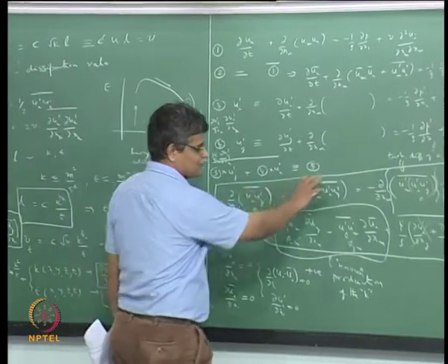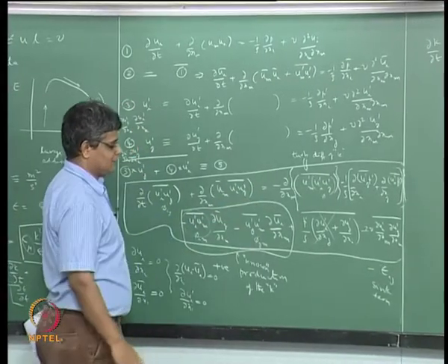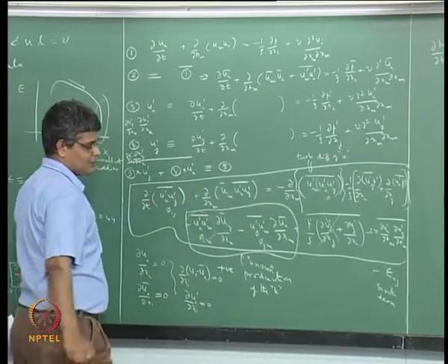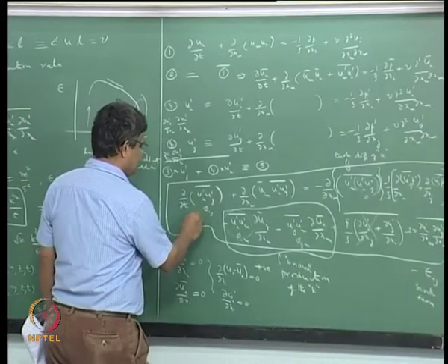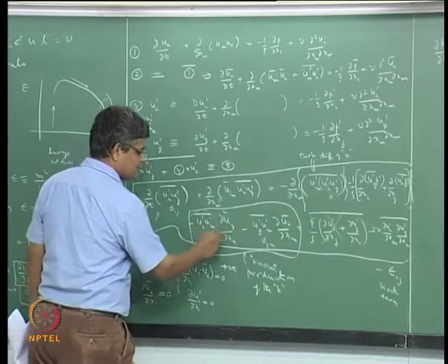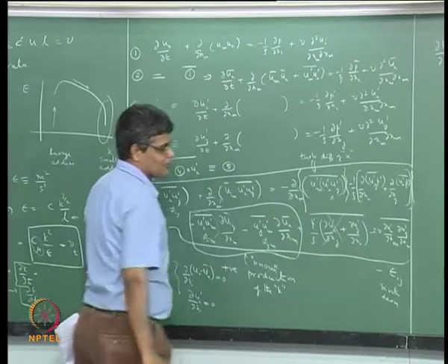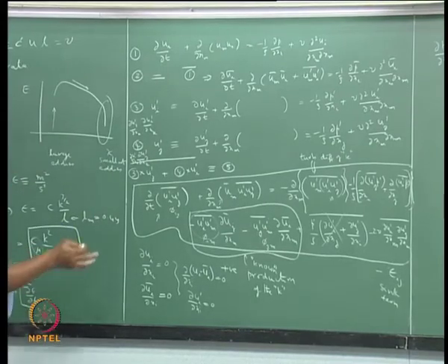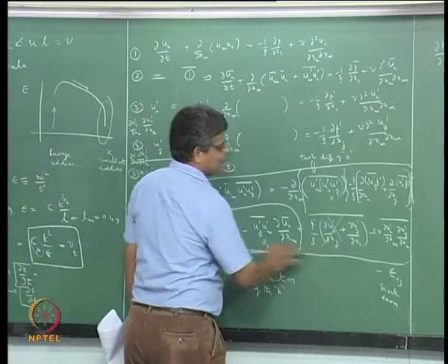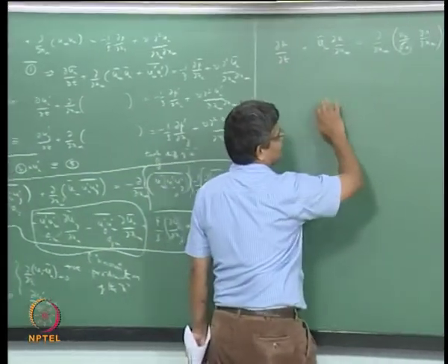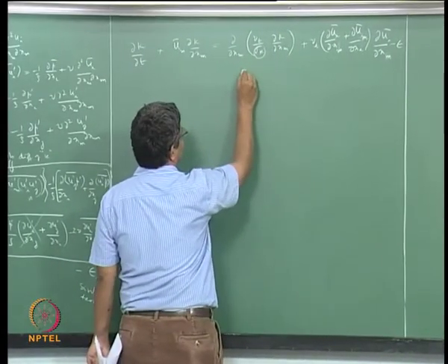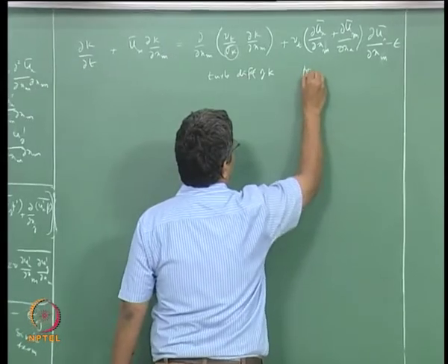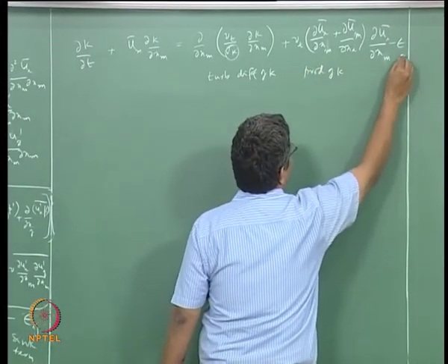Okay, so just as in this equation, this is the exact equation without any assumptions here. This is derived wholly from the Navier-Stokes equations and the continuity equation, and in this we can identify this term and this term readily, and we can identify some elements of these terms, but there are a number of terms which are not identified. The number of terms which are not identified for the epsilon equation is much more, and all of them are swept under these generic terms. Okay, these will be exact. You have a diffusion. Okay, so one can say this is turbulent diffusion of K, production of K, and this is the dissipation of K.